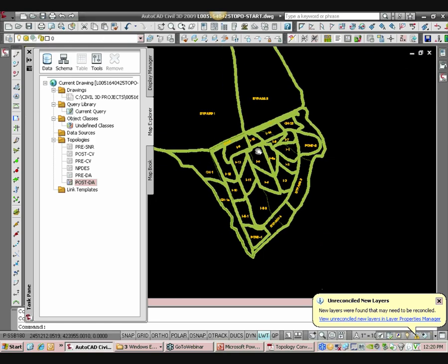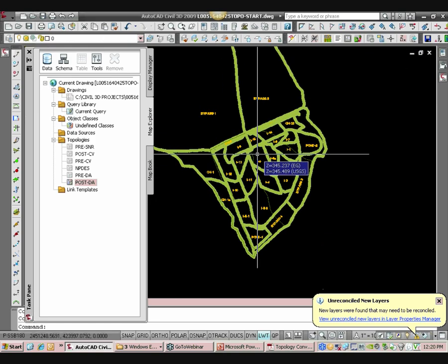That same thing I did, creating a topology, you have to do that for soils, and you have to do that for cover and your drainage areas. You have to make 3 topologies. Okay? Soils, area, and cover. After that's the hard part. After that, the rest is really automated from this point forward. It's just copying and pasting some stuff here and there. Okay?